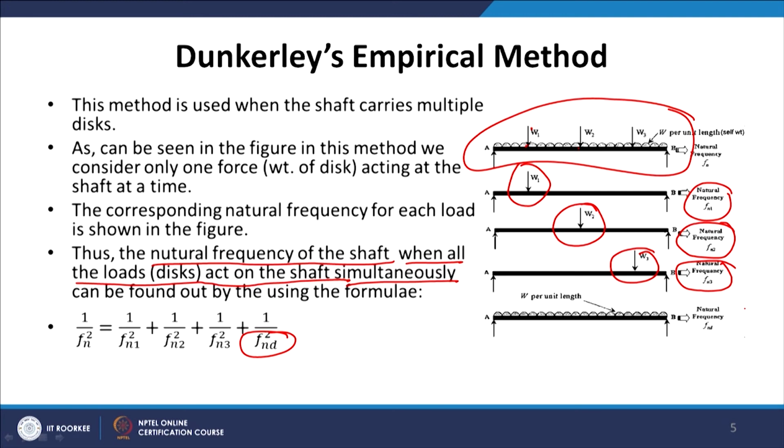So here we see that we can find the critical speed of a multi-disc shaft or multi-rotor shaft, because critical speed is nothing but the speed at which the speed of the shaft coincides with the natural frequency or natural speed of the shaft. At this speed, the vibration amplitude of the system becomes quite large or very excessive, and therefore we need to find these critical speeds. For a multi-rotor system, we discussed three methods. In the first method, we used the shaft in the vertical plane, a lightweight shaft, and using the flexibility influence coefficients we can find the natural frequencies of the system.